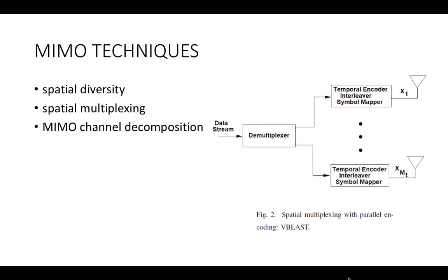The resulting symbol-to-transmit-signal mapping function is called a space-time block code. Although many designs of space-time block codes exist, additional properties such as orthogonality of the matrix allow improved performance and easy decoding at the receiver. Such properties are realized by the so-called Alamouti space-time code.